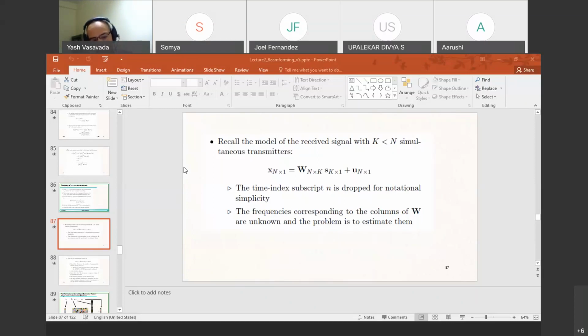Essentially, in the ideal form of the power spectral density, we get a spike wherever there is a signal present, and everywhere else there is a noise field. And then we saw that ideal PSD, which is just a summation of many spikes, is only approximately estimated by this DFT-based filter bank. There are problems of low resolution, smearing, leakage, energy leakage, side lobes, etc.